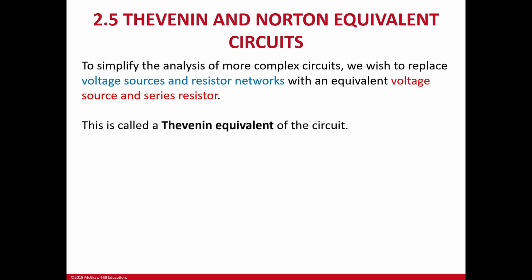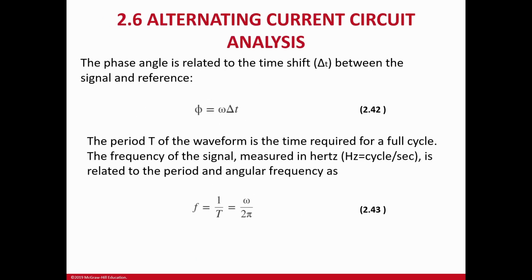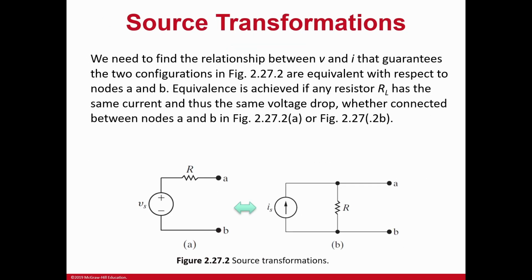Okay, and let's move on to this slide. We know this is called source transformation from electrical engineering. This is a Thevenin equivalent with a voltage source and a Thevenin equivalent resistor connected in series. And this is also equivalent to the current source with the Thevenin equivalent resistance. The resistance is the same between these two, but it's connected in parallel. So this is the whole concept.